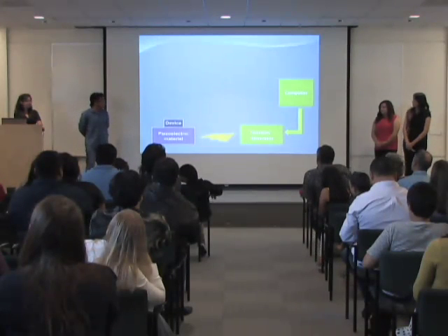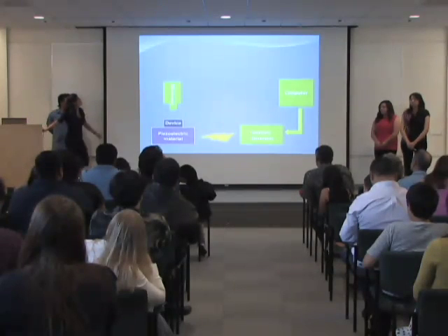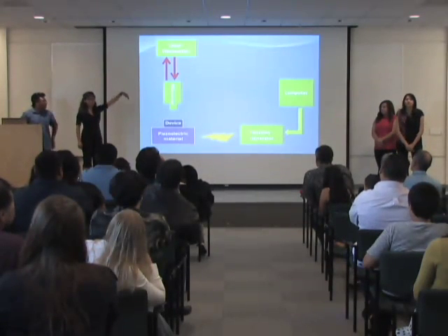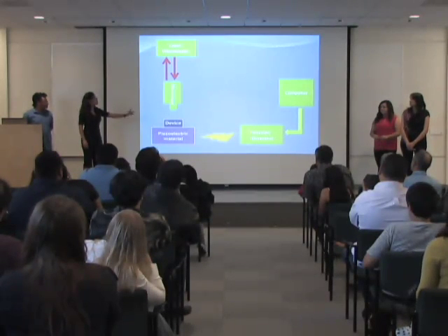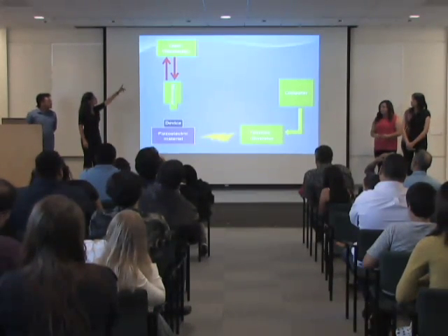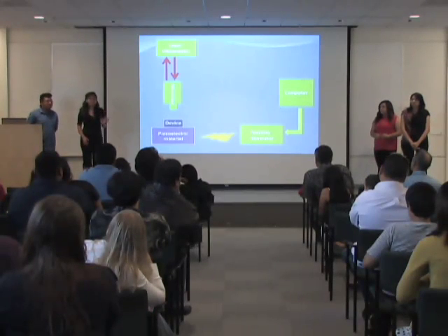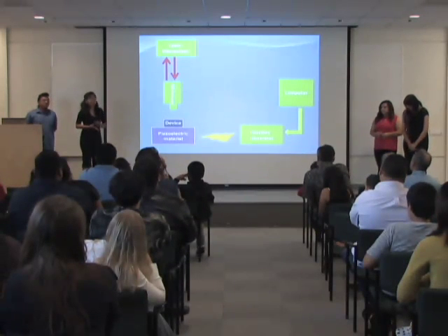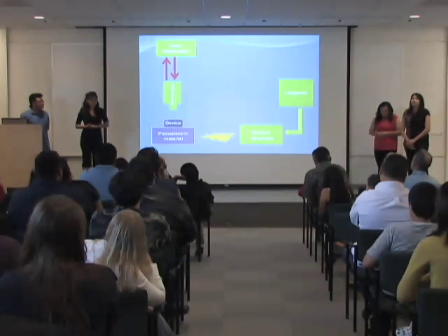This whole thing is then put underneath the microscope. This microscope is attached to a laser vibrometer. The laser vibrometer shoots down a laser beam to the microcantilever, which sits on the device. The beam shoots back up, and the laser vibrometer reads it. The laser beam is Doppler shifted. The frequency of the laser beam is Doppler shifted, and the laser vibrometer is able to convert it. It's able to represent velocity in terms of voltage.